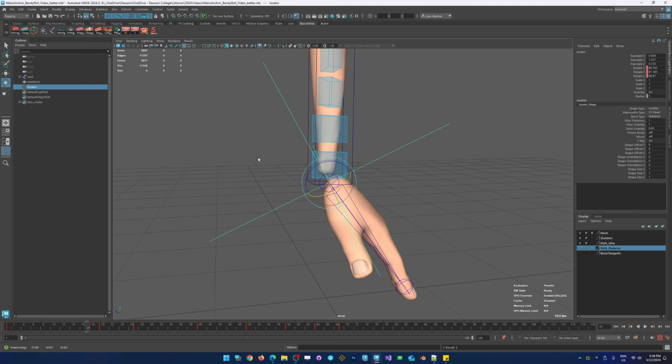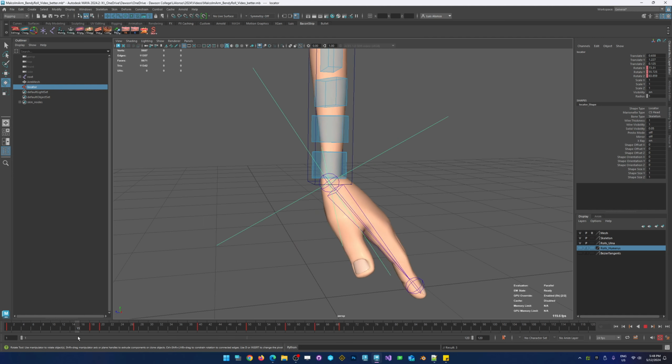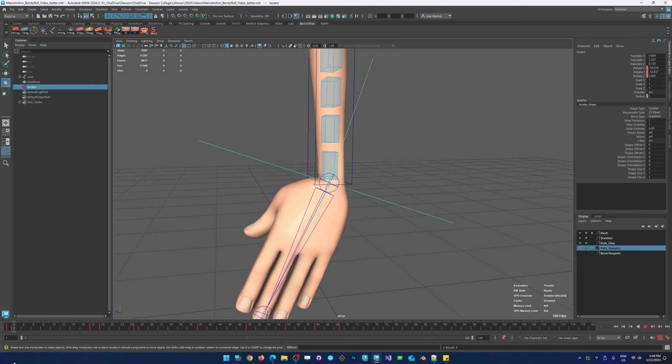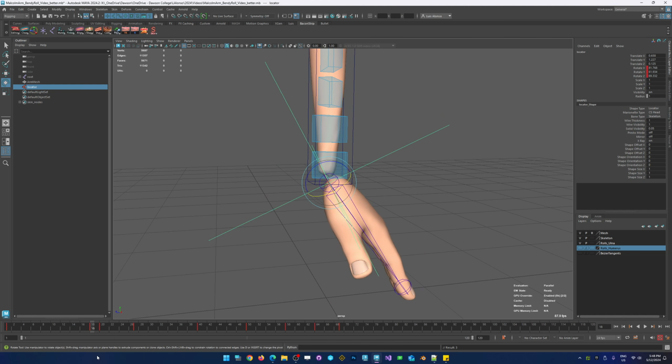Anyways, point is, if you look carefully, you're not really far from the initial position, like the initial rotation. So my point here is that even though this method overall is good, and we reinforce this method thanks to the knowledge we have from the basics of rigging, when we were able to get this to be pretty decently reliable, it still has a lot of issues where it can break, and you're at the mercy of quaternion, or rather Euler issues that can come in here.